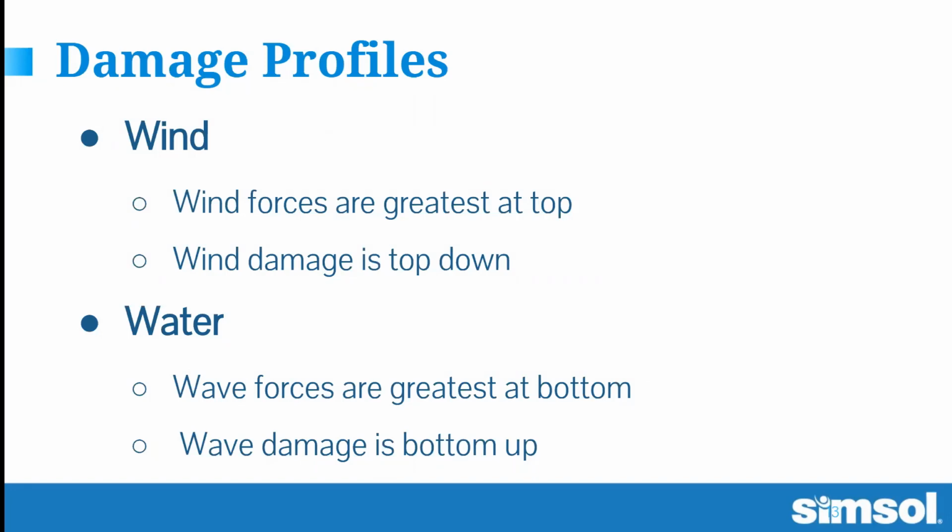Now with surge in particular, it's very difficult to get that wonderful picture where you have the standing or ponded water line with that seed line that you can measure, because remember, the waves on the ocean are still occurring every 6 to 12 seconds. So as that storm surge is slowly making its way out of the property, going back into the limits of the beach, those waves are lapping constantly. So it's basically self-cleaning up after itself as it goes. So it's very difficult to find that ponded water line.